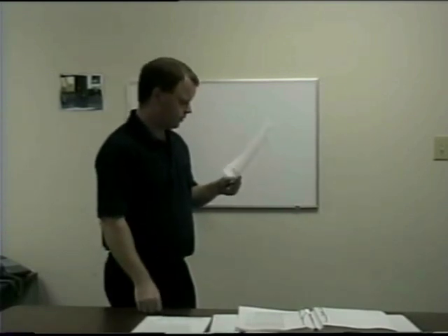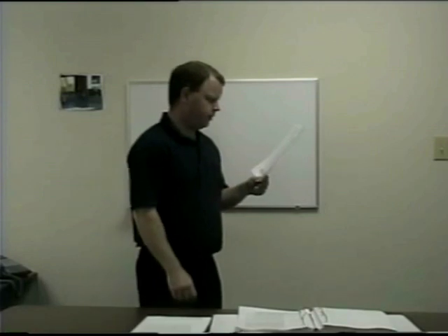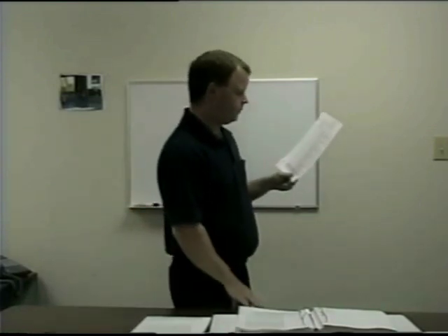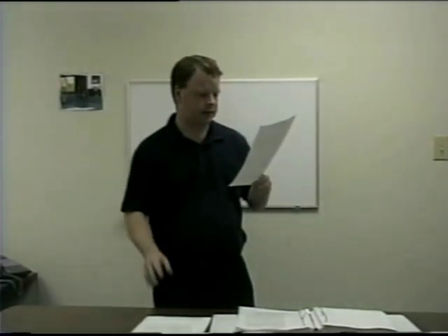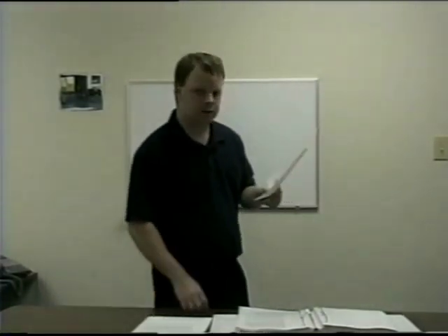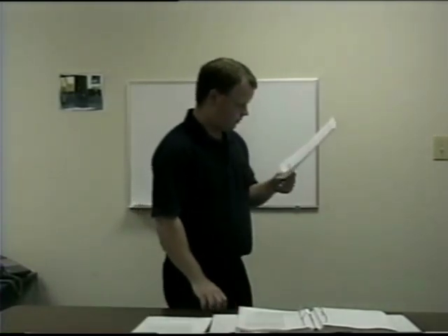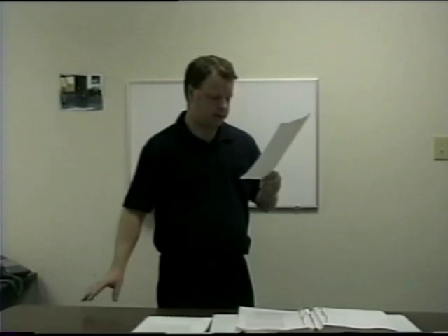Lath and plaster. Verify anchorages, blockings, and plates required for other equipment, support, and fastening are provided and installed. Let's be on top of that, before we get covered up and have to tear stuff out. Verify corner beads, expansion devices, vents, screeds, casing, trim, and other accessories are provided and properly installed.